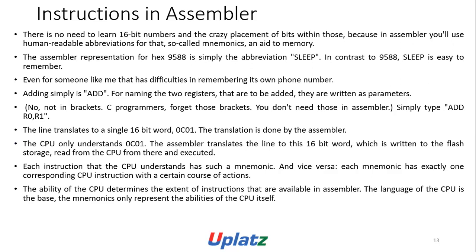In assembler there is no need to learn 16-bit numbers and the crazy placement of bits within them, because in assemblers you use human-readable abbreviations, so-called mnemonics, as an aid to memory. The assembler representation for hexadecimal 9588 is simply the abbreviation SLEEP. In contrast to 9588, SLEEP is easy to remember. Even for someone like me who has difficulty remembering his own phone number, adding is simply ADD.